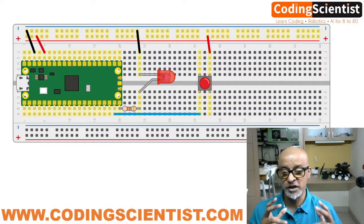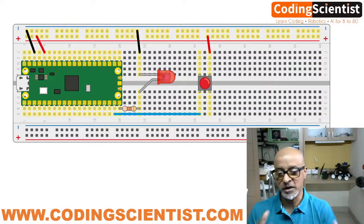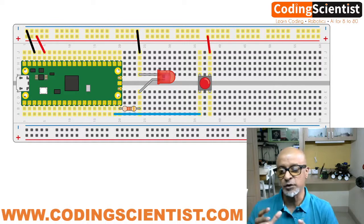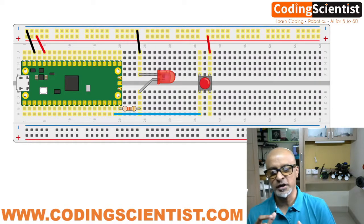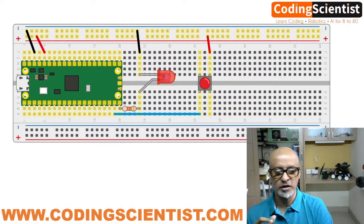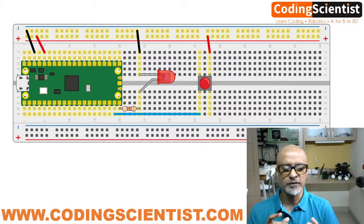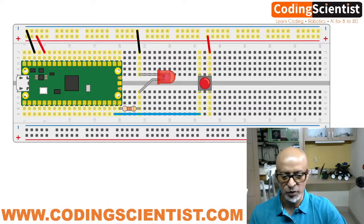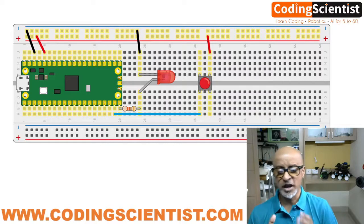In the previous lesson I showed you how to connect an LED with a current limiting resistor, anything between 50 to 330 ohms, to the positive terminal of your LED and connect it to pin number 15. The same circuit we will use with additional wiring for the push button. So what is the use of this? Basically the push button controls the input and output logic in MicroPython code.